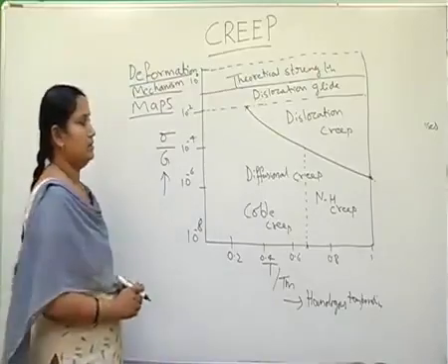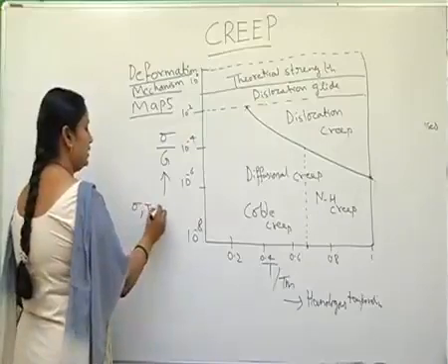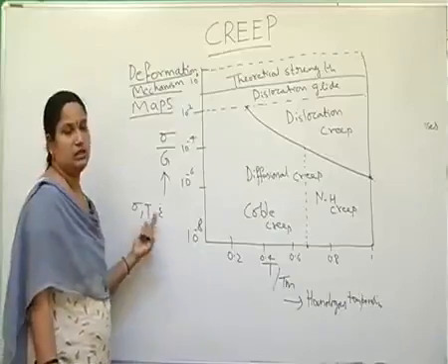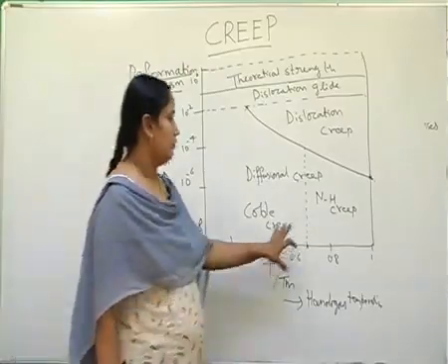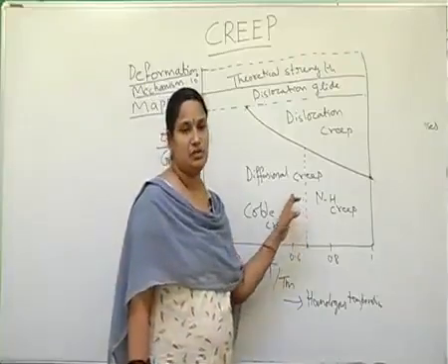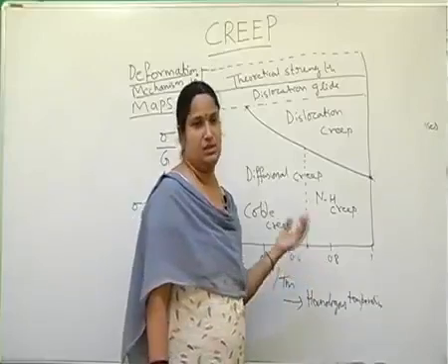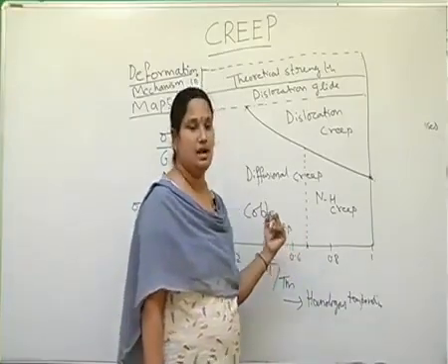By plotting the strain rates also, we have three variables: stress, temperature and strain rate. Knowing any two of these, the third can be predicted very easily. So if Coble creep is the dominant deformation mechanism, then a material with a coarse grain size has a very low creep rate, and the creep resistance of the material is higher.